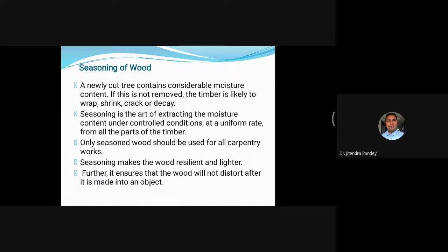That means we can define seasoning as the art of extracting the moisture content under controlled conditions at a uniform rate from all parts of the timber. That is called seasoning of wood. And when you obtain seasoned wood, it gives a very good, metallic sound. If a metallic sound comes, that means your wood is very well seasoned.